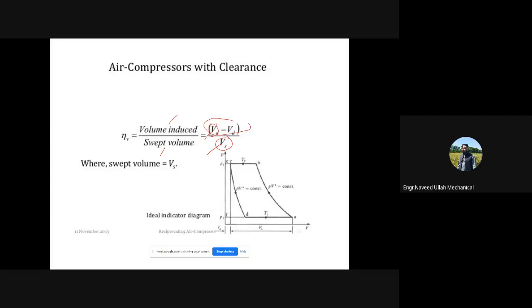और इसकी रीज़न क्या है, वो मैन्युफैक्चरर को पता होता है कि भाई टोटल वॉल्यूम ऑफ द सिलेंडर इतना है, तो मैंने वो क्लियरेंस इतनी रखी है, तो स्वेप्ट वॉल्यूम हम कैलकुलेट कर सकते हैं. ये तो हमें क्लियरेंस वॉल्यूम यहाँ से आ जाएगा, ठीक है, लेट्स से वो 6% क्लियरेंस रखता है, तो दिस विल बी योर क्लियरेंस वॉल्यूम. तो नाउ योर टोटल वॉल्यूम माइनस योर क्लियरेंस वॉल्यूम विल बी योर स्वेप्ट वॉल्यूम. इसका मतलब ये है कि यू कैन कैलकुलेट योर स्वेप्ट वॉल्यूम. सिमिलरली दिस इज द टोटल वॉल्यूम ऑफ द सिलेंडर, ठीक है, ये पता होता है. VD को फाइंड आउट करना थोड़ा सा मुश्किल होता है,